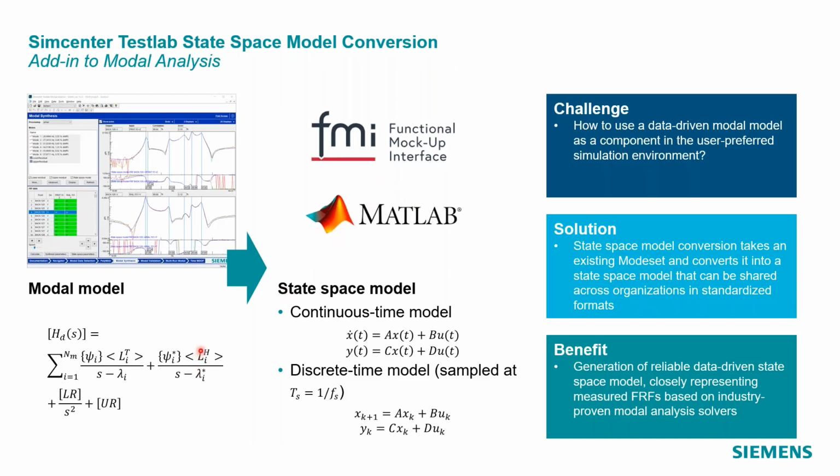What is the idea here? The idea is to take a model, as I was explaining before. So we have mode shapes, natural frequencies, damping ratios. And we want to put that in a model that also can be used in other environments. And then a state space model is very well suited. It's a kind of an input-output model.